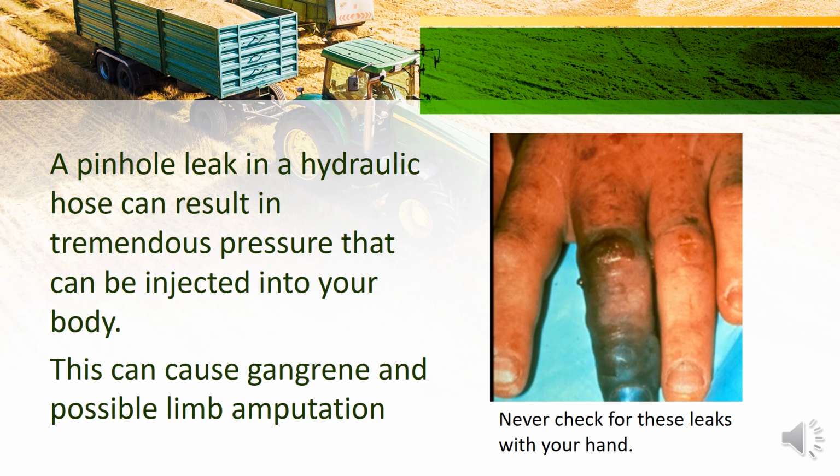If you do get an injury from a hydraulic pinhole leak, it can cause gangrene and possible limb amputation. And here's a picture of somebody who got a pinhole leak where the chemicals were injected into their body and their finger became gangrenous.